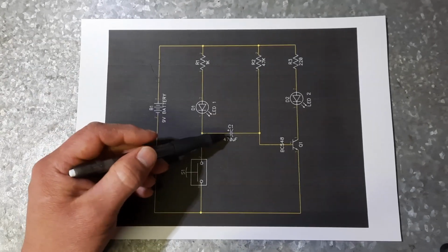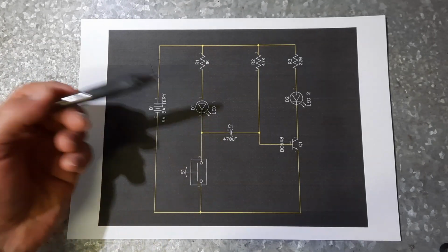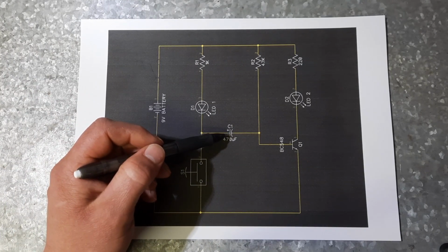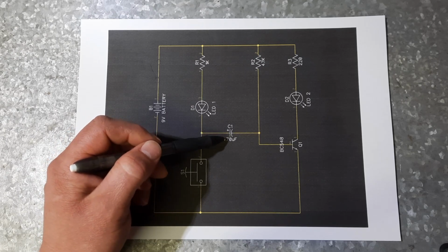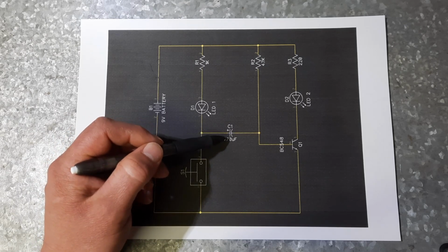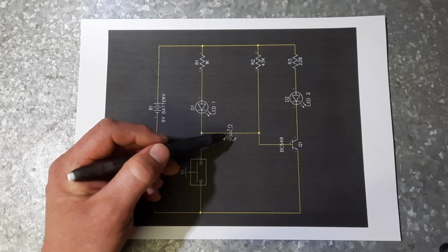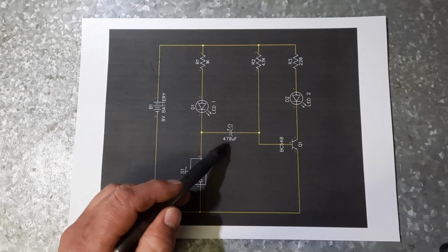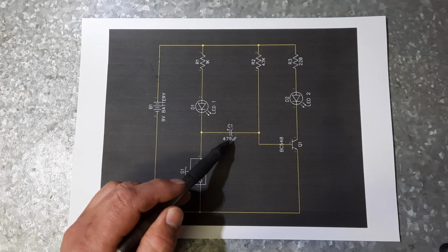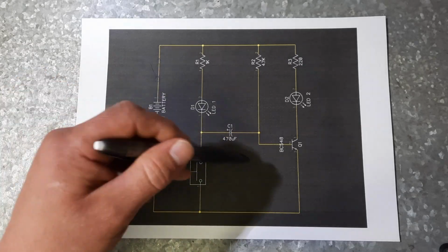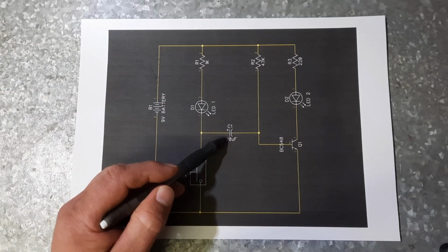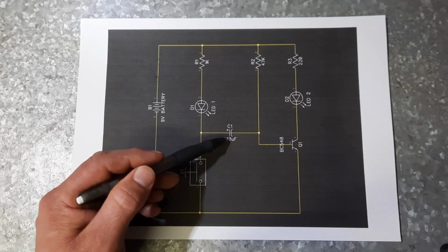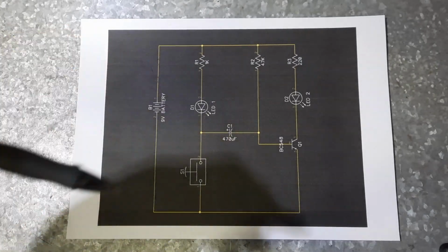So a capacitor, this is a polarized capacitor, meaning it has a negative and a positive. I've heard people try and explain these as batteries. They're not. It's erroneous to think of a capacitor in a circuit as a battery. So a battery has a chemical process that's happening inside the battery, which is producing the electricity. Whereas a capacitor has 4 states. It's either discharged, charging, charged, or discharging. Back to discharged. There is no chemical process happening inside that capacitor. We need to give it an external force to charge it. We need to give it voltage to charge it.